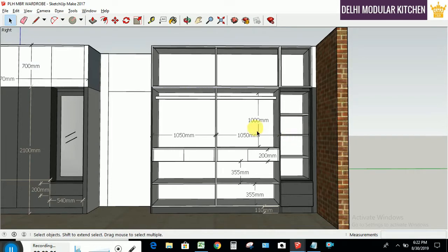The top and bottom pieces we can extract from one plywood. There will be a little bit of wastage that we will use for the drawers. One ply for this internal middle vertical and these fixed shelves, so a total of 2 ply. For these 2 shelves we need half a ply, so 2.5 ply, and the remaining half ply will be utilized for the drawers.